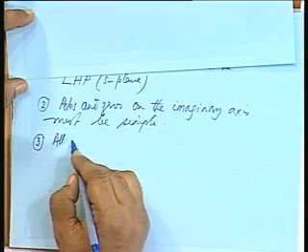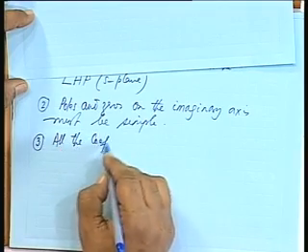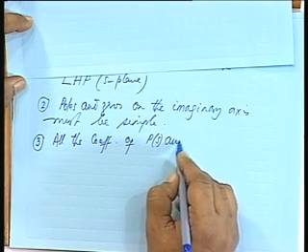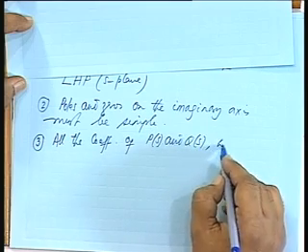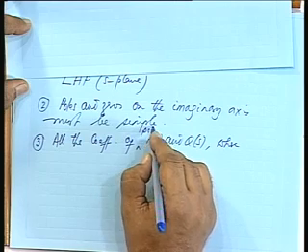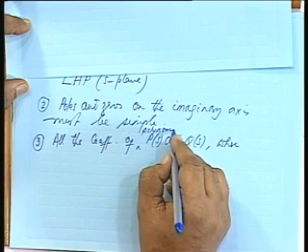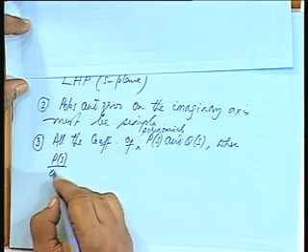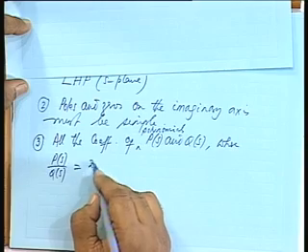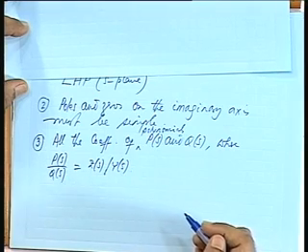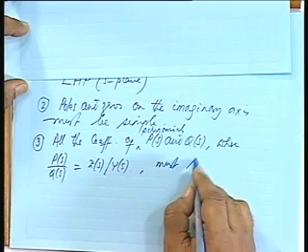Is that all right? So, all the coefficients of polynomials Ps and Qs, where Ps by Qs is the driving point admittance or impedance function, must be positive.